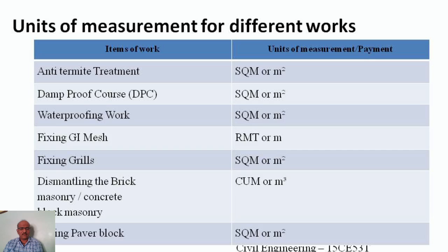Fixing of grills is measured in square meter, and dismantling of brickwork, masonry, concrete work is measured in cubic meter, and paver blocks, laying of paver blocks is also measured in square meter.